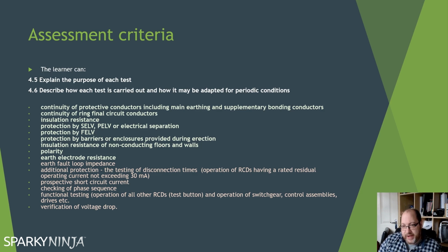So when you look in the wiring regulations and you have your maximum values of measured earth fault loop impedance calculated, or you refer to the tables, they are using Ohm's law from the time current characteristics within Appendix 3. So that is the purpose of the earth fault loop impedance test. It's one of the most important tests, because again, the whole principle of an inspector is to verify that the wiring regulations protection for safety, Chapter 41, has been complied with, and we do that with earth fault loop impedance tests fundamentally.